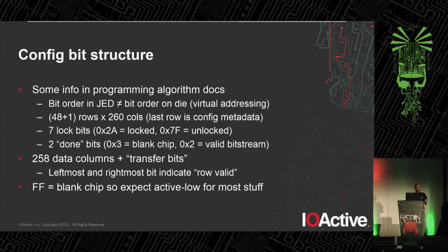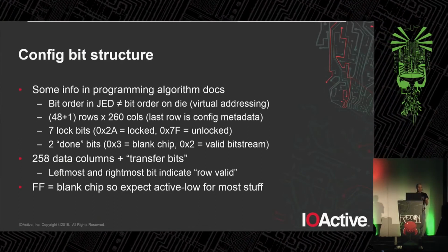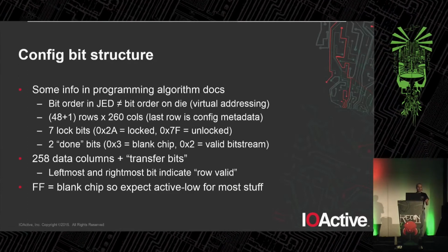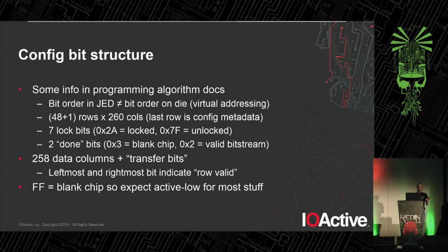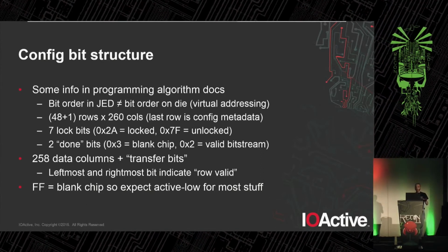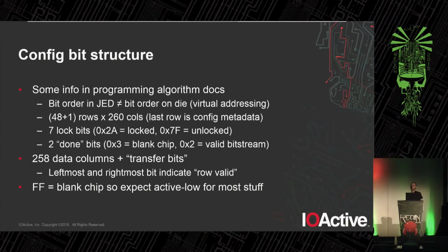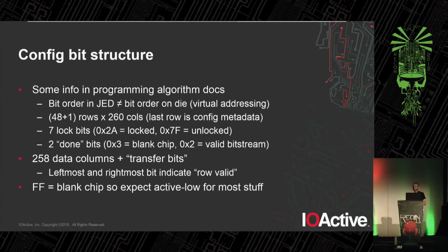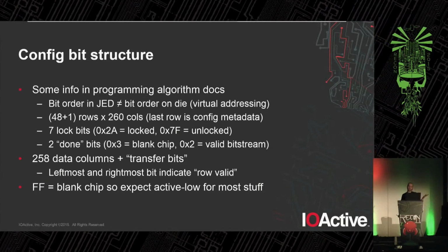The other intuition we can get from this is that since it is EEPROM-based, FF is going to be the state of the memory when the chip is blank. Therefore, we expect most of the memory on the device is going to be active low. So most things should be turned off when the bit is high and on when the bit is low. We just don't know exactly what that bit does yet.